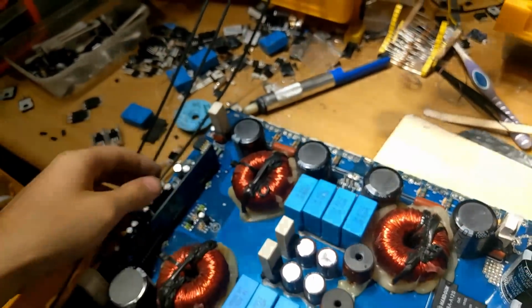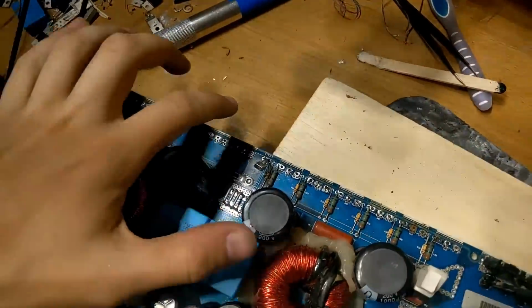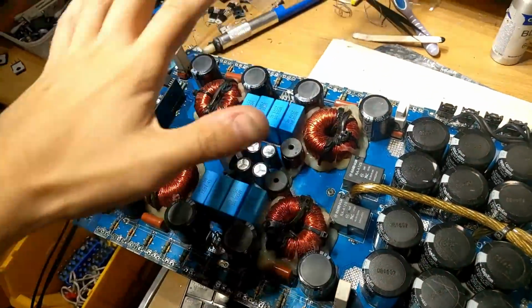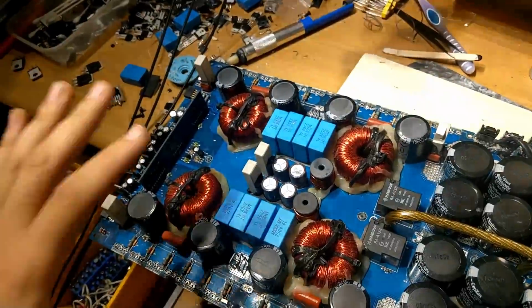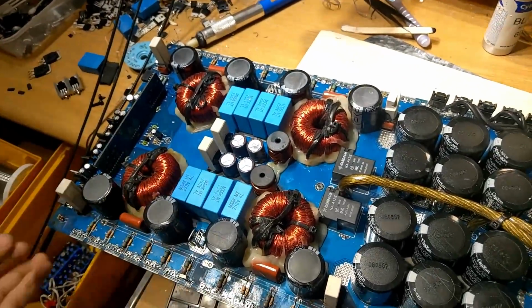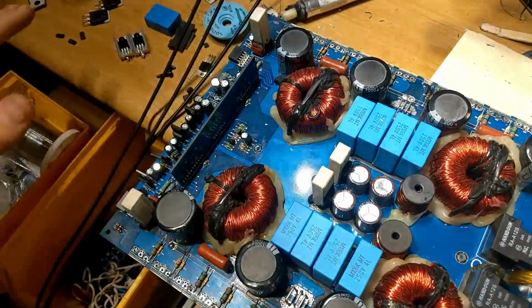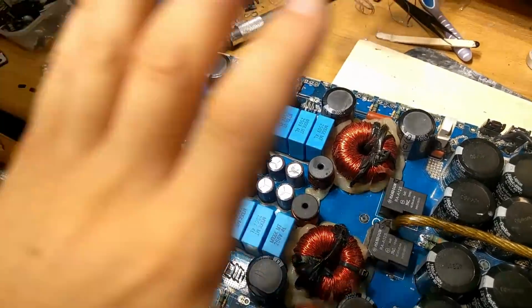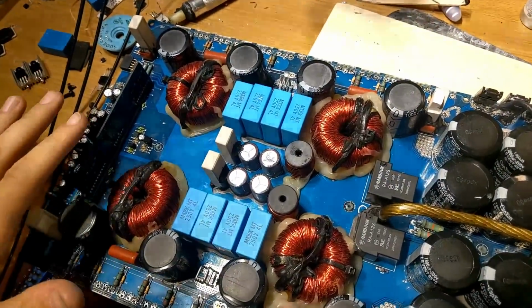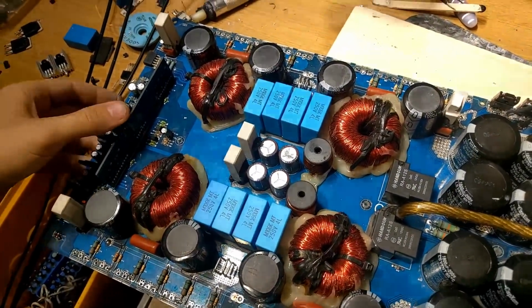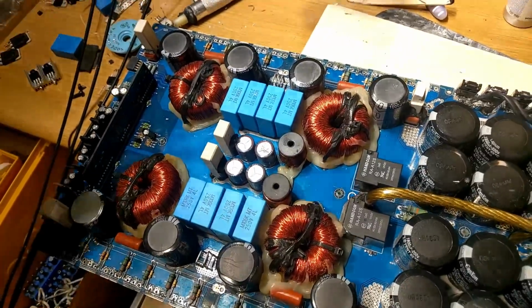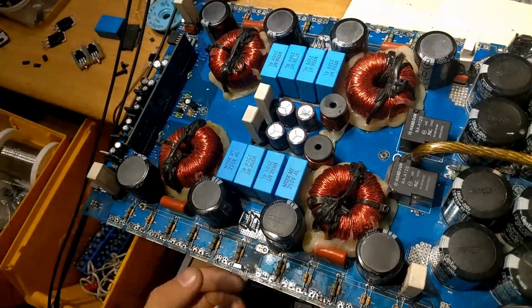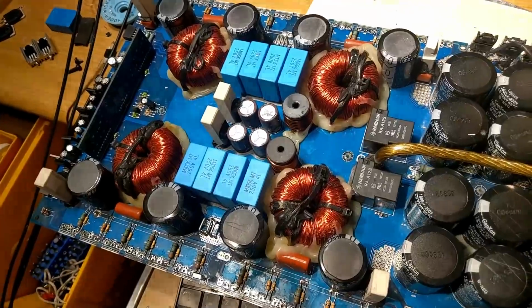to test the amplifier out to see if there is low side switching on the output section. If I'm happy that the output section comes on and it's going to switch the FETs on and off properly without causing any more damage due to anything else on the board that's bad, then only then will I fit the output FETs. So I always check through before I fit the output FETs, making sure that I'm happy with how the circuit is acting, making sure the drive waves are beautiful and perfect before I fit any output FETs, and we should be good to go on this one.